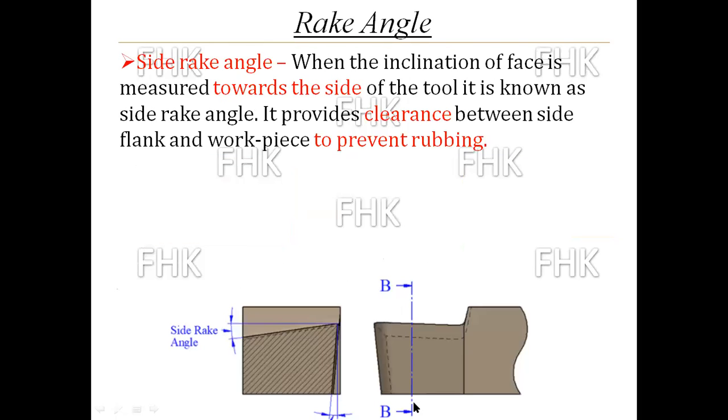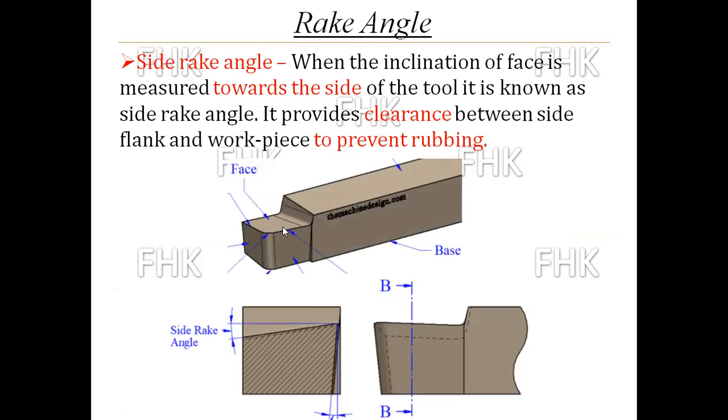Now, in the same category, the side rake angle. When the inclination of the face is measured towards the side of the tool, it is known as the side rake angle. And this side rake angle you can see in side view.